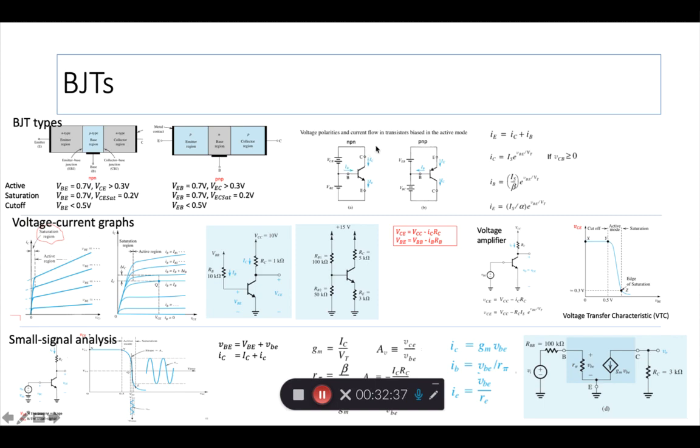The reason we do that is because we always believe that the physically higher points are at higher voltages and current flows downwards, right? We use that throughout our circuits courses and chapters. To follow that same rule, this is the best way to draw circuits. Because the collector is always at the highest positive voltage, it's at the topmost point, the base is somewhat lower, and the emitter is at ground, and it's flipped around for the PNP.